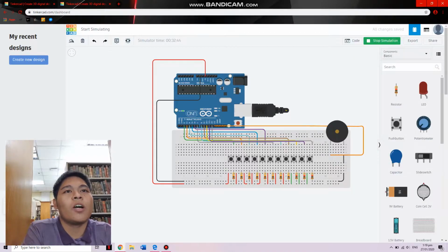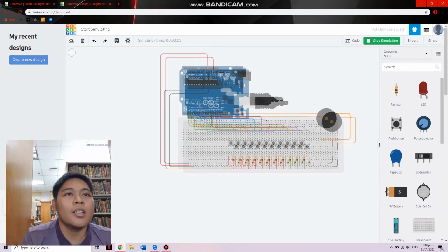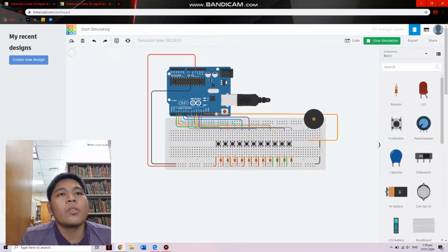I am Lauren Del Mundo, and I am here to discuss the use of resistors in the Arduino circuit. When building your Arduino projects, you use resistors to limit the amount of current going to certain components in the circuit, such as LEDs and integrated circuits. In our prototype, we used the push buttons and the piezo. The 11 push buttons located here are each supplemented with their corresponding resistors, and each is further connected to the piezo to produce a sound.